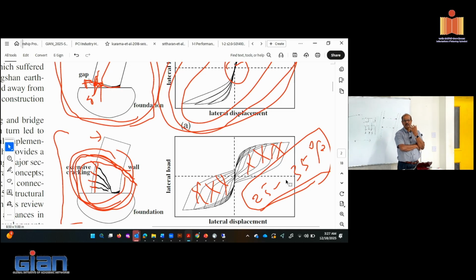But in one structure, there was some floor damage, and they had to remove the floor diaphragm partially, and found that they used a lot of weld between beam and columns to establish their connections, just like precasters will do. They have to establish those connections. Those welds were broken. And then they started inspecting almost every steel structure, and a significant percentage of steel structures actually experienced weld damage. So then that industry wanted to come up with a new plan as to how to deal with it, and they went through a series of experimental evaluations and established new connections.